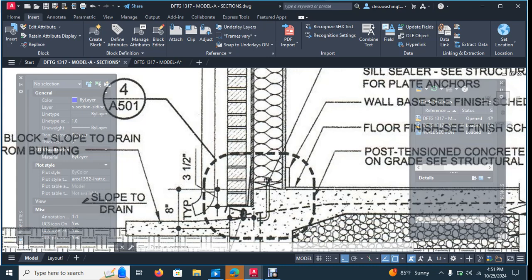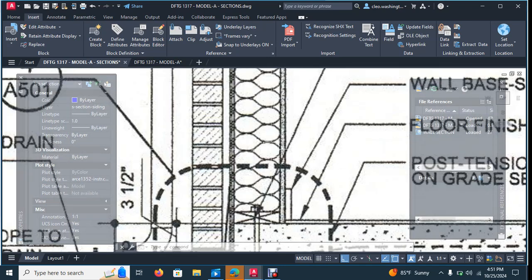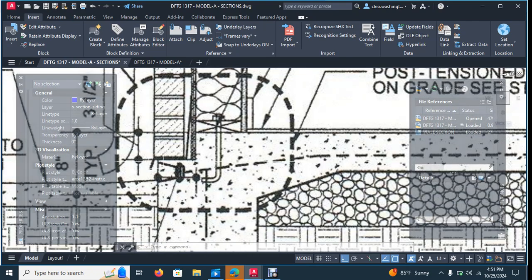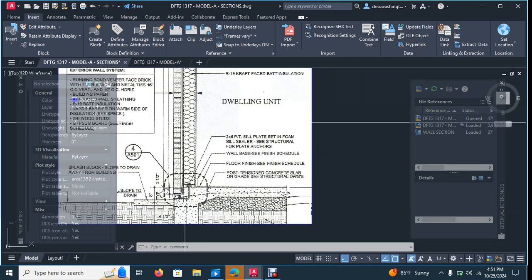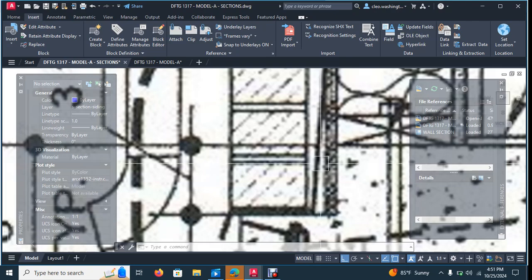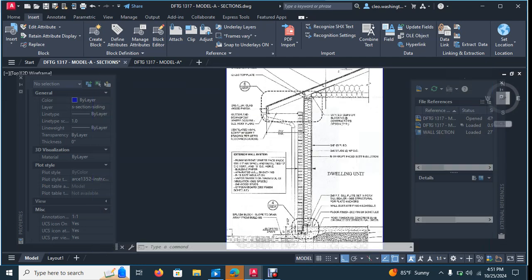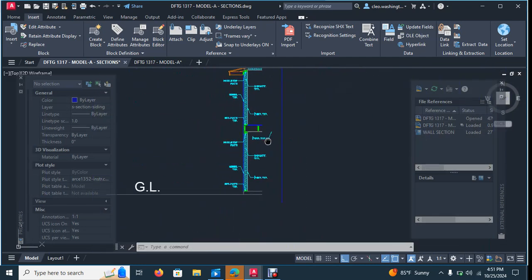But if you have 4-inch walls, I know a couple of students did talk to me about it. That's okay. But I want to go ahead and straighten it up. We'll have an exercise on an assignment where we go back and get all of the wall thicknesses correct, if you haven't put the proper 6-inch nominal, 5.5 actual walls in. Okay. So what they're showing here is a 6-inch exterior wall, a sheet of 3/4-inch plywood, and then what's called a waterproofing membrane. This little thing that you see right here keeps the moisture out of the building, okay? And it goes all the way up to the top. So first things first, let's just start right there, okay?